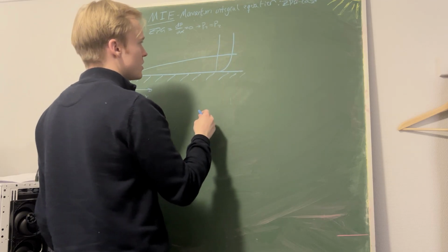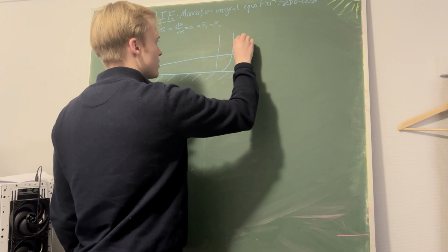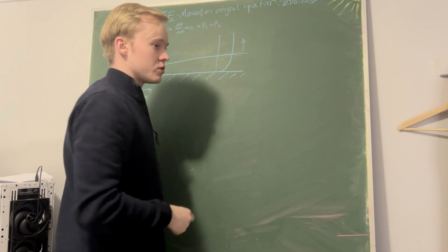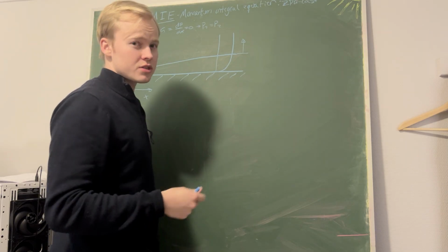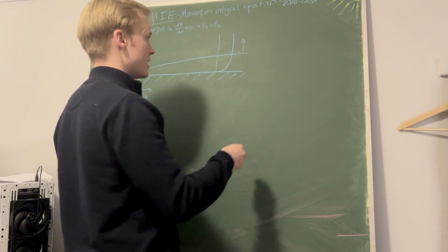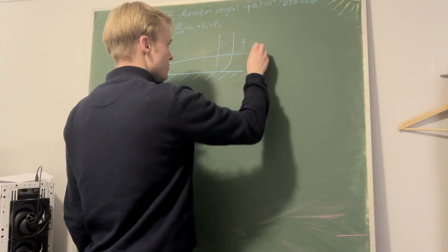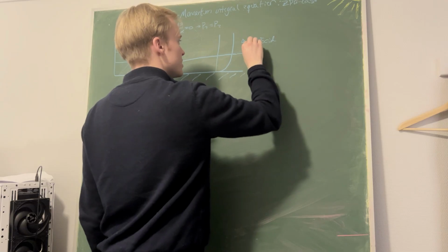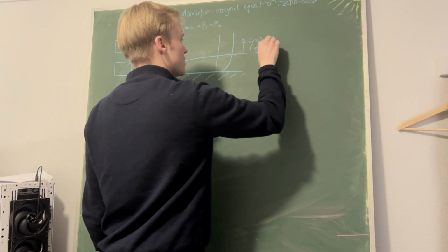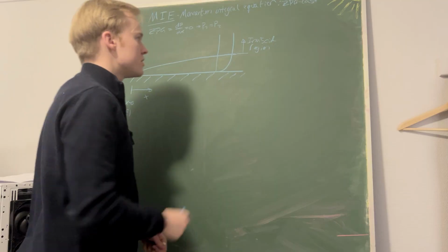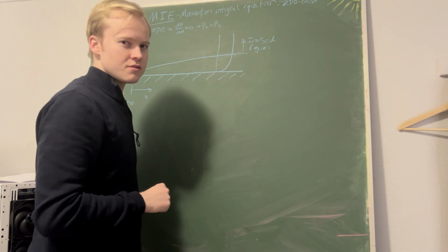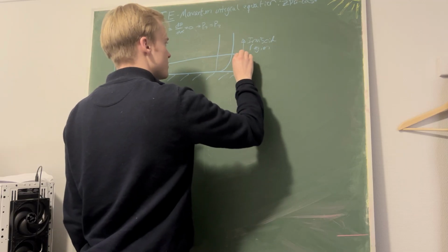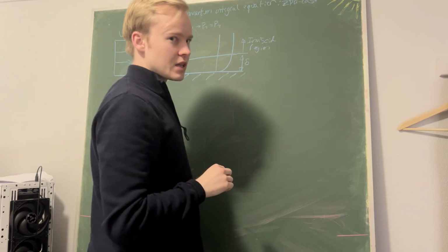And what is important to say here is that over the boundary layer we have what's called the inviscid zone. There is no viscosity, you could say it as that. So this is like the inviscid region. It's far away from the wall, even though the boundary layer itself is very short and thin. So this is what we call the boundary layer, or the boundary layer thickness, delta.